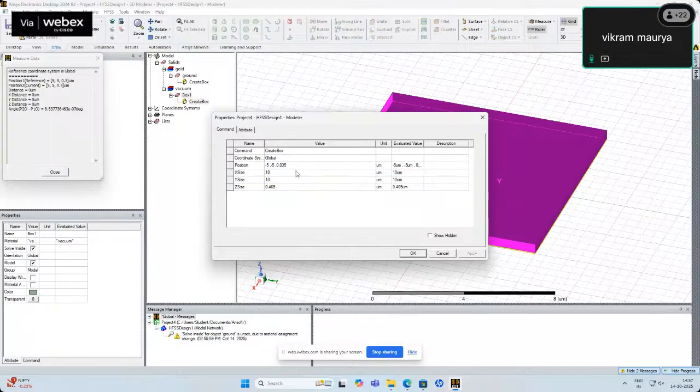Okay, so now if you very clearly notice, this position is again very important. This position is important for one reason, and that is the z coordinate of this position. This z coordinate is 0.035. As we said that 0.035 is our TG or ground point. Okay, so it immediately knows that the substrate is on the ground and it is starting from TG only. So our initial coordinate for the z-axis is TG itself, and then the substrate will be mounted on that ground. So it will start from TG and it will go to the height of the substrate itself.